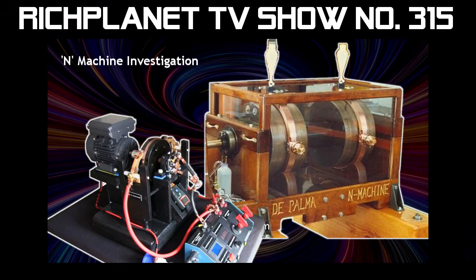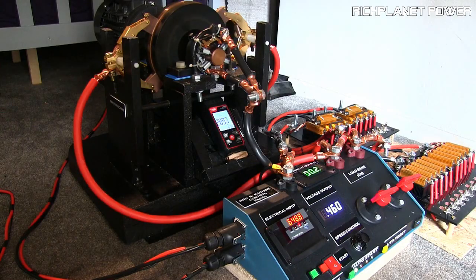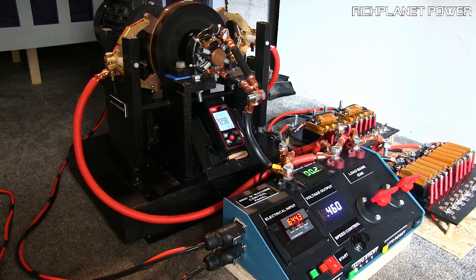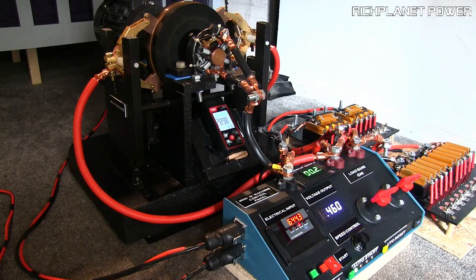Now, I recently built a co-rotating homopolar generator in order to investigate their claims. It is essential that you watch show number 315 in order to understand what was built and what it does. As I explained in the previous video, my machine is not capable of producing more power out than in due to the fact that I am using carbon alloy brushes, which produce a significant amount of drag on the rotating machine. And this drag absorbs an amount of power from the drive motor which is well in excess of the electrical power output capability of the machine.